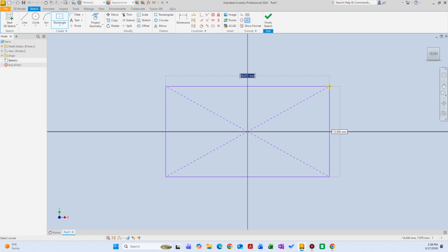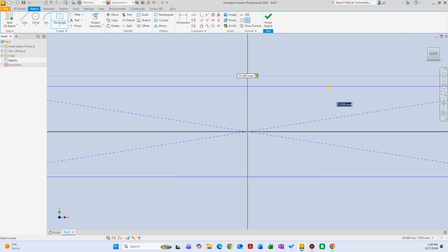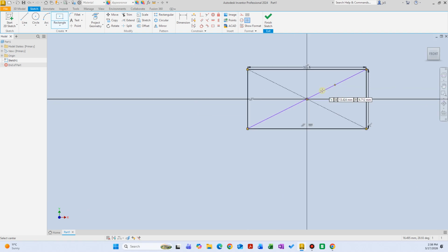I have been using millimeters as my unit of measure since the beginning of this tutorial. I could change it to inches for this exercise video, but I didn't want to, and I wanted to show this little trick. I think I mentioned it once before as well. Instead of changing those units and the settings every time you work with a different unit of measure, you can just come here and instead of entering millimeters, you can enter 4IN, and it's going to recognize it as inches. And you can hit tab and go to the width, and you can enter 2IN. It's going to recognize it as 2 inches.